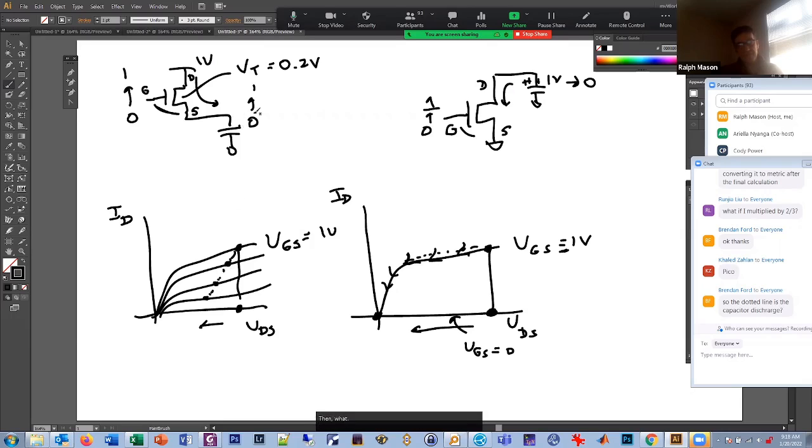Then what happens is, as this gets up to, in this case, 0.8 volts, the gate source voltage is going to become 0.2 volts, and this transistor is going to turn off. So in fact, if you look at this trajectory, it will stop right here at VT. The drain source voltage will be VT. So the highest this can get is 0.8 volts. It can't go all the way to 1 volt. And that's bad news. That means when I tried to pass this 1 volt through there, I didn't get up to 1 volt. So it wasn't very good at passing a 1.